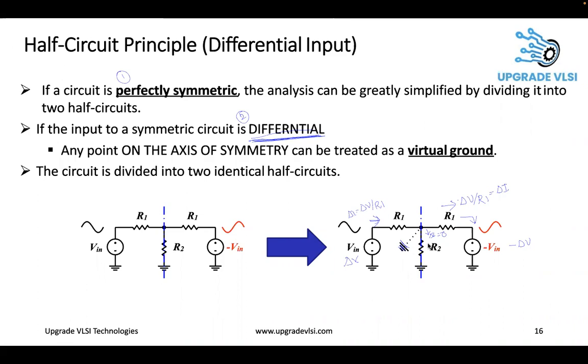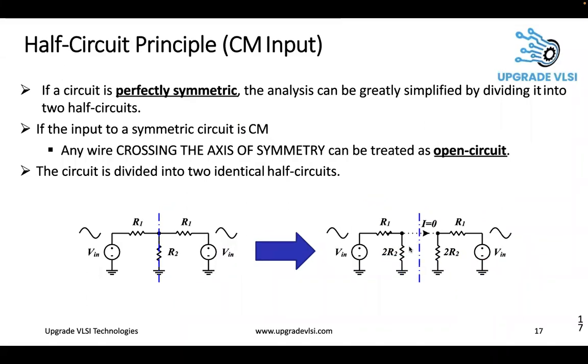So any questions on this? No, sir. Okay. So now we know that this is virtually ground. It means that I can write it something like R2 is not taking any current. So I can split it into two parts. So let's see what happens. R2 is split into two parts now, R2 and R2. So even if I connect here, the current that is flowing here is zero.